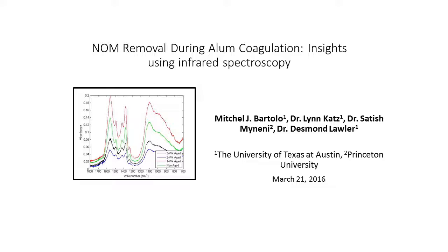There's sensitivity there. We would like to think that when we're removing the DBPs, THMs, we're not just removing the chloroform and then allowing the brominated ones to sneak up closer to that 60 mark where we're still in a safety margin. But if you're removing 60% as opposed to 25%, you're potentially going to have a higher percentage of brominated ones, but they're still being removed.